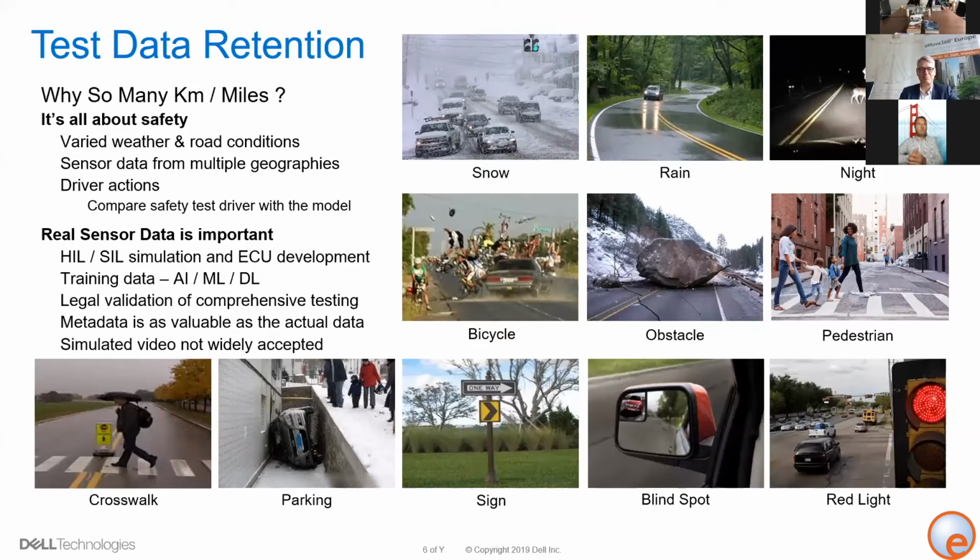Just to name a few, companies are focused on hardware in the loop testing, software in the loop testing, model in the loop testing, vehicle in the loop testing, driver in the loop testing. We have to cover the legal validation of these algorithms. And we have to also focus on synthetically generating these scenarios, because very often it is too dangerous to collect an incident or a scenario in the real world.